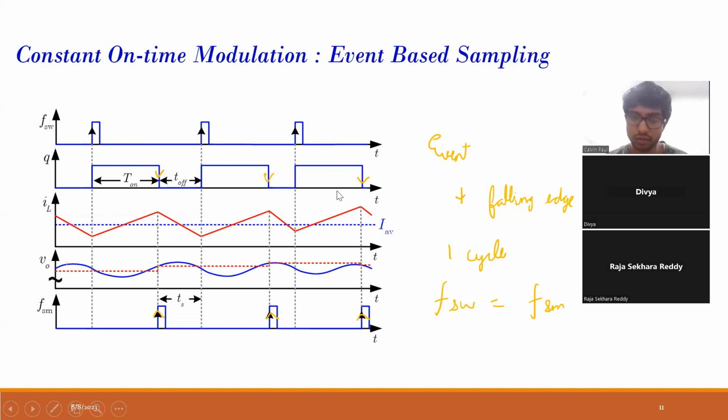So here, how will we account for the delay from input to output of the ADC, the transmission delay? In these waveforms, we are not actually showing you the delay. But in the practical scenario, the delay will be like this. It takes a sample over here, but it gets converted and shows up over here. We take the sample over here, but only after this time will it give you the updated value.